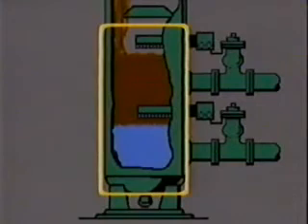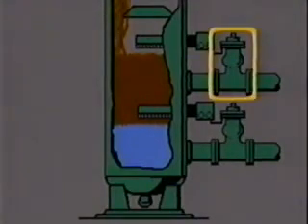Oil and water fall to the accumulation section, where gravity separates the oil from the water. Since the settling time is longer than gas-oil separation, the liquid must remain in this section longer than in two-phase separators. This requires a larger liquid accumulation section. The oil leaves the vessel through a liquid level control valve in the oil portion of the accumulation section. Water leaves the separator through a different liquid level control valve. Both the oil and water valves have liquid level controllers.